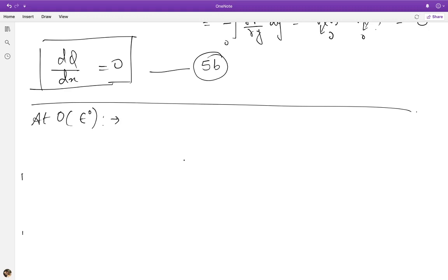So although the equations are the same, what has changed is that the boundaries have now come to conform with the Cartesian coordinate system, which immediately allows us to recognize from the fact that v is equal to 0 at y equal to 0 and at y equal to half, that we can simply say v is equal to 0 throughout the domain, which satisfies dv by dy equal to 0 and both boundary conditions, which is not possible when we had the wavy wall.